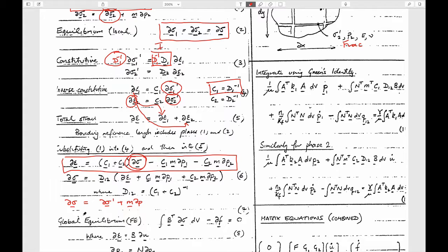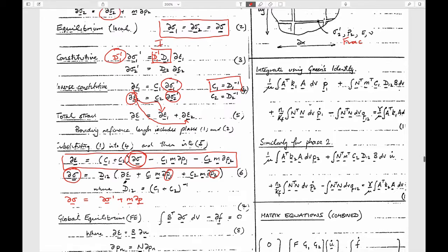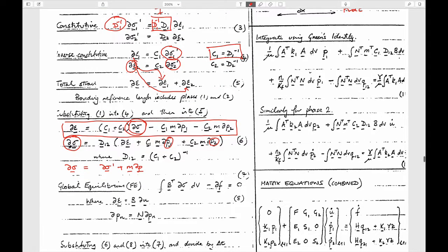That was basically our statement of Terzaghi's law. If we do it for the dual porosity system, we still have total stress, which is what we're going to write our equilibrium equation in, but now it's defined in terms of the fluid pressures, not just in one medium, but in the fractures and the pores, and also in terms of the deformation of the solid medium, the composite medium.